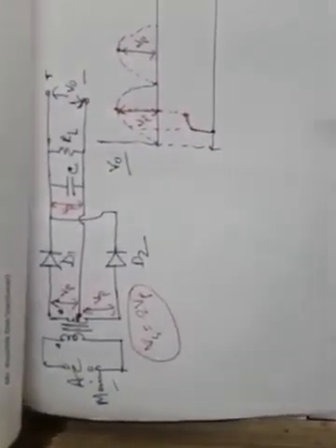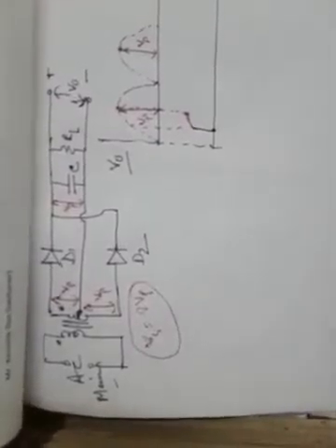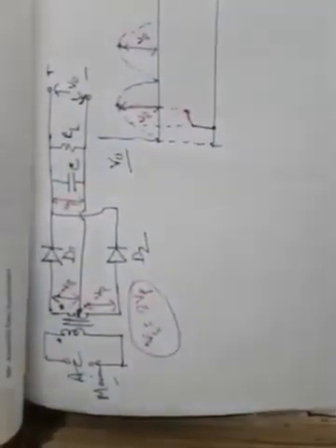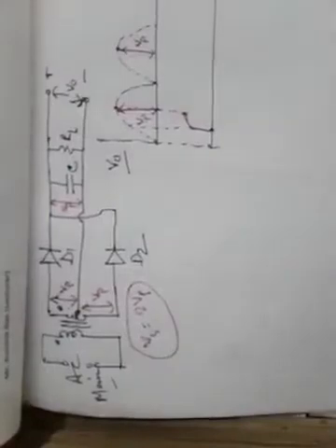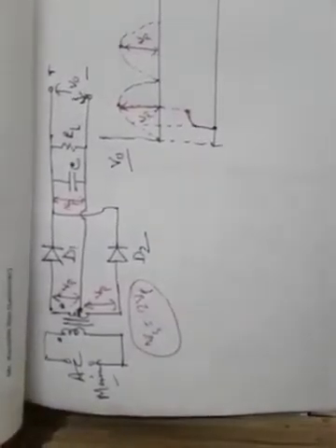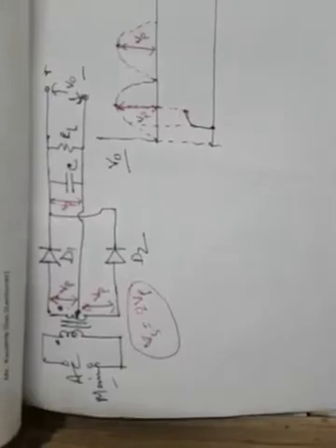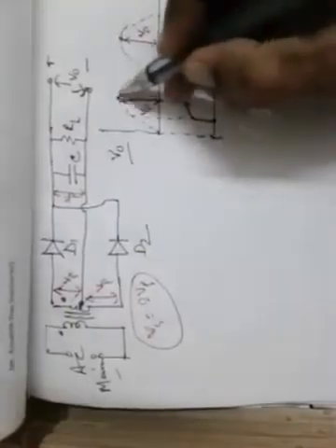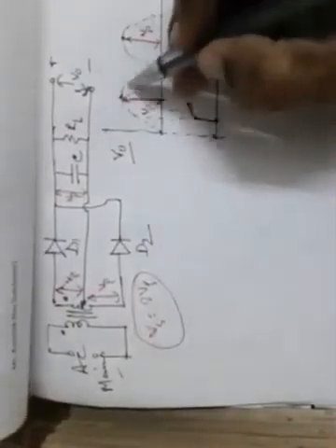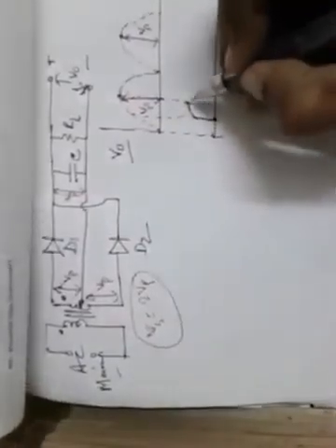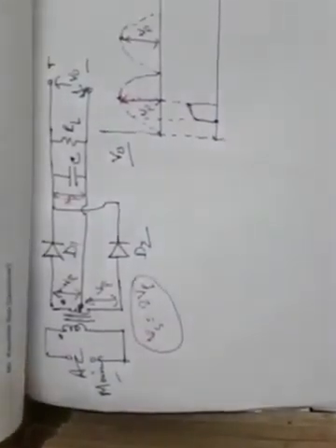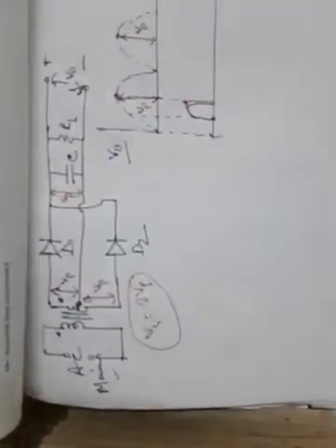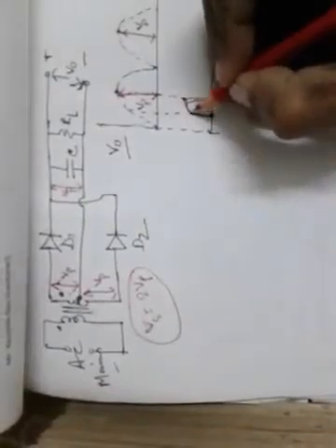So as a result of that, there will be no further conduction of current to the output side through this diode, and the capacitor will try to remain at its peak charge Vp. Now, we can see that at this point of peak charge, when due to the natural nature of the input signal it starts to decrease, the diode conduction will be stopped. So the diode current will come down to 0 once again. So the diode current will look like this.